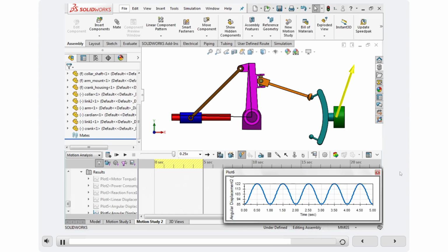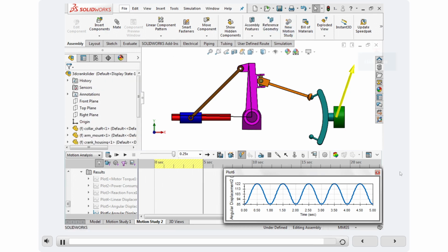The plot shows the angle between the line defined by vertex 1 and vertex 3, and the line defined by vertex 2 and vertex 3. Vertex 3, therefore, defines the center point. Notice that, in the present case, the limits of the angular motion are 85 degrees and 122 degrees, giving a range of 37 degrees. Click Save and close the file.